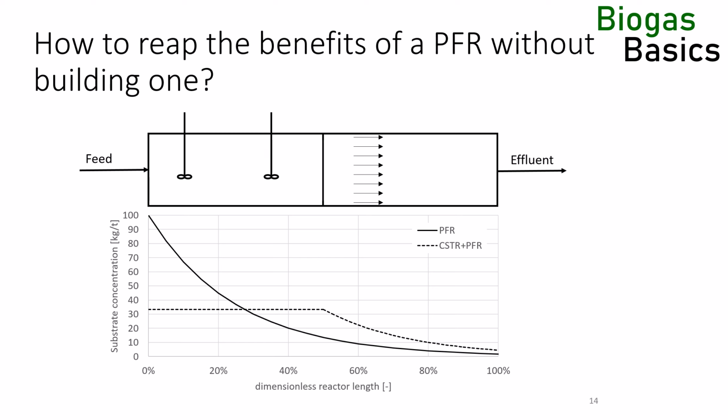The minimum residence time must be proven with tracer studies. These biowaste fermentations often use structural material like straw, hay, or green cuttings to stabilize the flow in the digester and limit axial dispersion. At the high TS concentrations in these flow reactors, the digestate is likely to show a yield stress, and the flow could in theory form a rigid plug. But mixing is required to degas the fluid, and that will introduce axial dispersion.